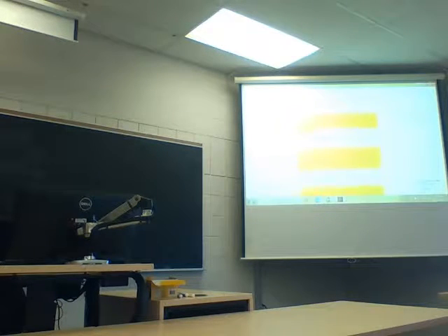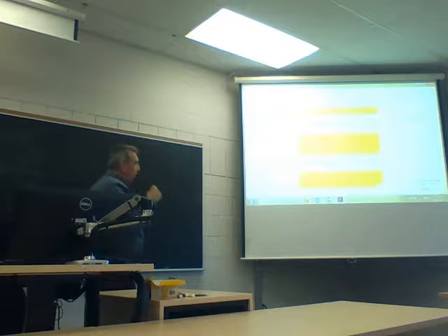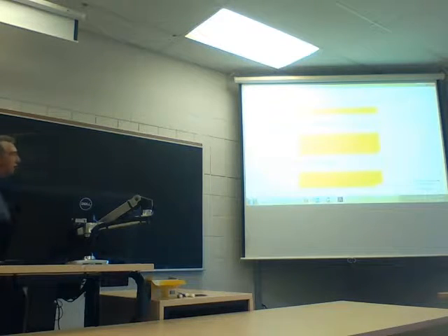Okay, effects of moisture. Moisture is not a good thing in a compressor. Moisture is really not a good thing at all. Moisture even on control systems is pretty interesting. I've had controls go down because of the moisture in compressed air. Especially if you have a window, it's a warm day and you're putting compressed air through a copper line, and then as it starts to cool down, it's going to condense and you start to get a freeze in the bottom of your control line.